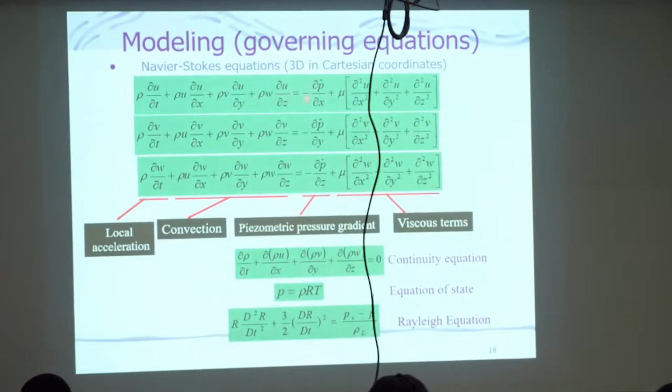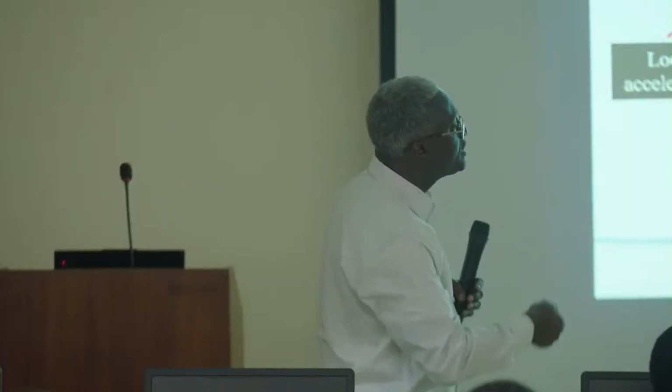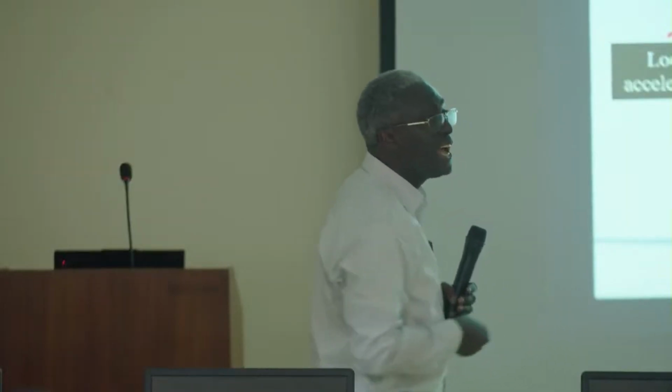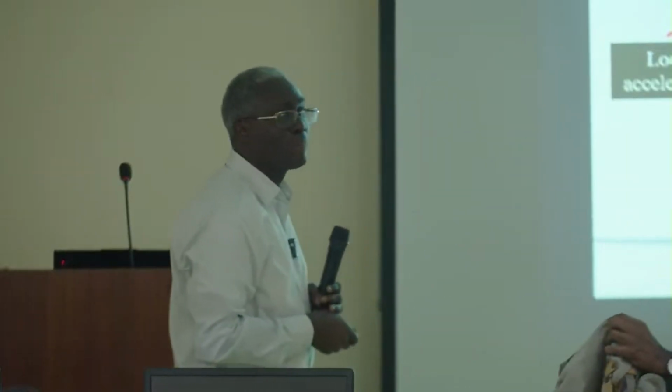And then we are saying that the local acceleration and the convection of the fluid have to be balanced by the piezometric pressure gradient as well as the viscous terms or viscous forces acting on the object.